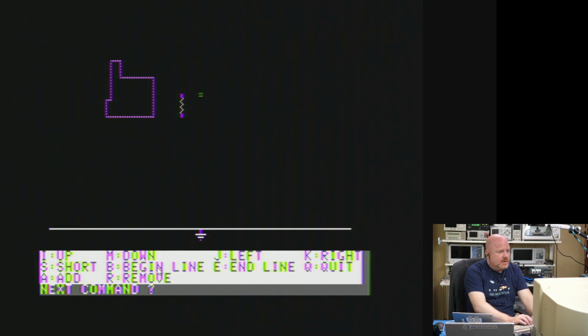So what I had done before is I did add, and then I typed in resistor, and it didn't take it. And then R, didn't take that, but it took RES. So I'm gonna try cap now. And then direction, let's go right. Parameter. I don't know, 10UF? Okay.